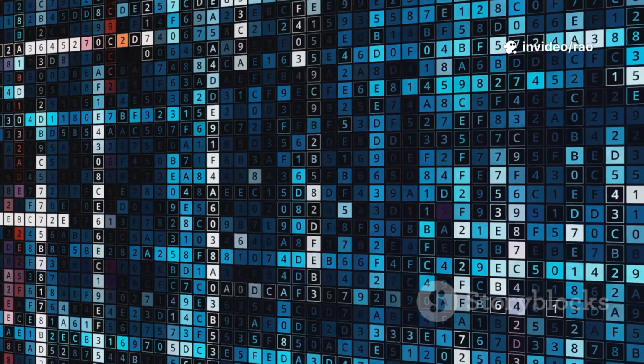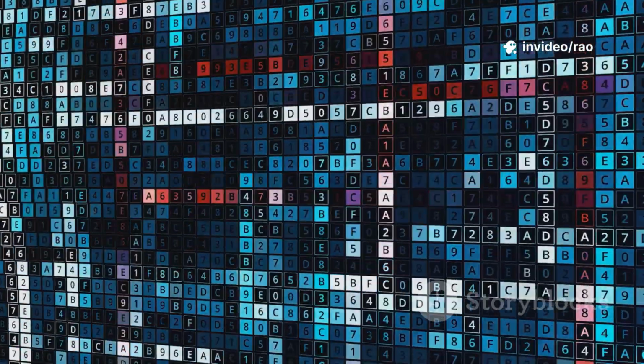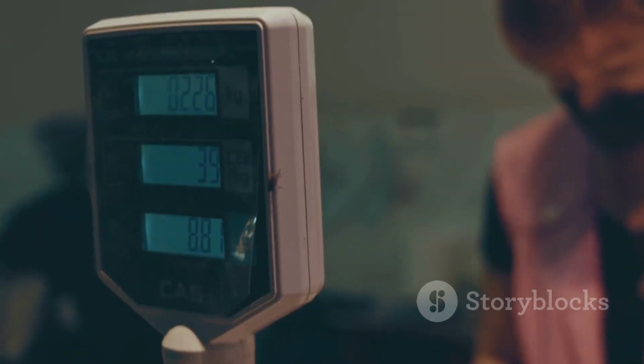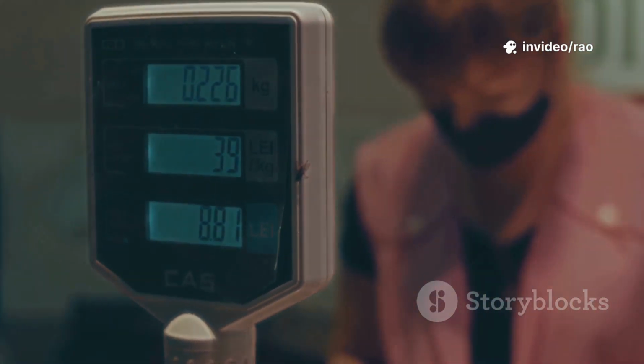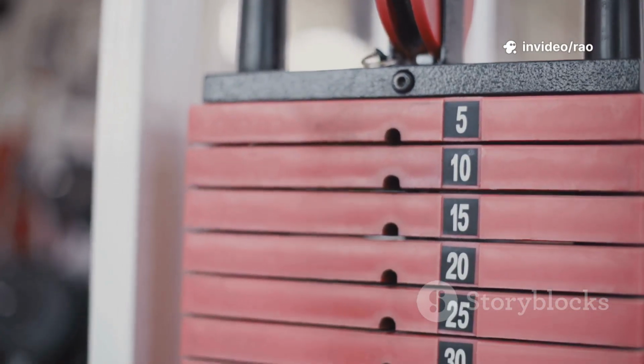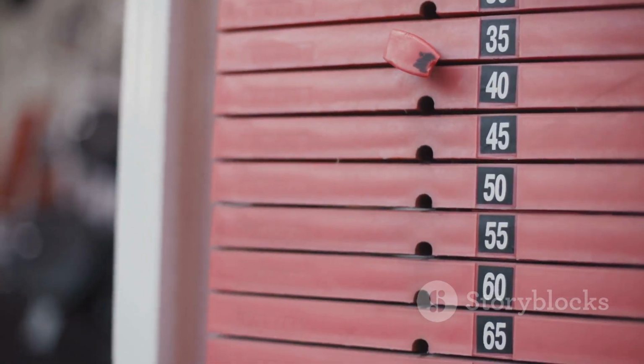For our 12 millimeter diameter bars, unit weight equals 12 squared divided by 162 equals 144 divided by 162 equals 0.8889 kilograms per meter, approximately. This value means that every 1 meter length of a 12 millimeter bar weighs 0.8889 kilograms.